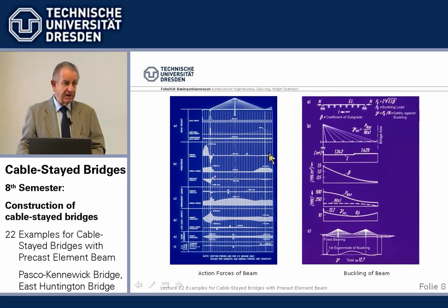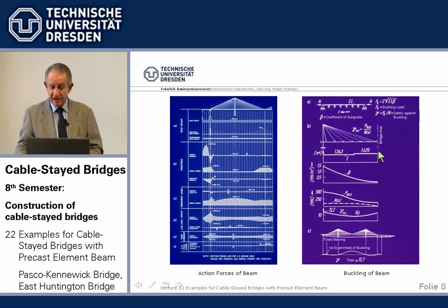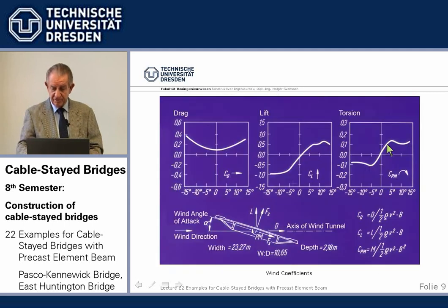Very briefly, you know the forces in the bridge. We've dealt with that in detail. We have here the loads, we have the post-tensioning. So in the end, we have here the run of normal forces from inclined cables and post-tensioning. There's a second order theory. We've gone through all that.